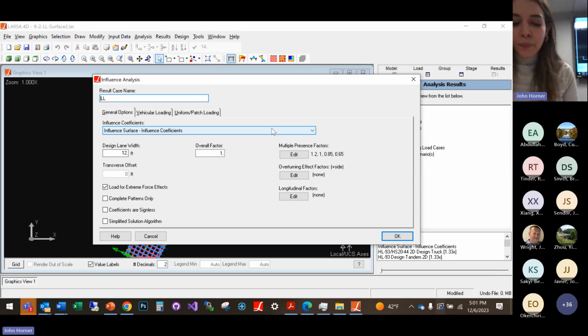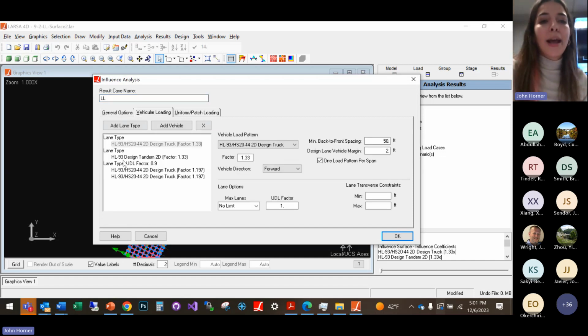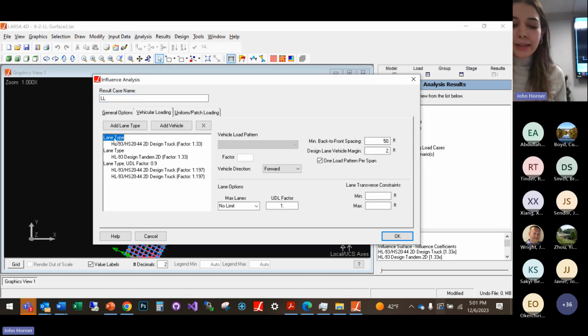This mode can also be changed to advanced, and in that case you will have some extra inputs, like minimum number of lanes. With this input, you can say that for a lane, let's assign minimum 1. In that case, this lane will always be kept on the surface, even if it does not contribute to the extreme case. This could be a rating condition for advanced rating. You will have another advanced option, used for lane placement but omitting results.